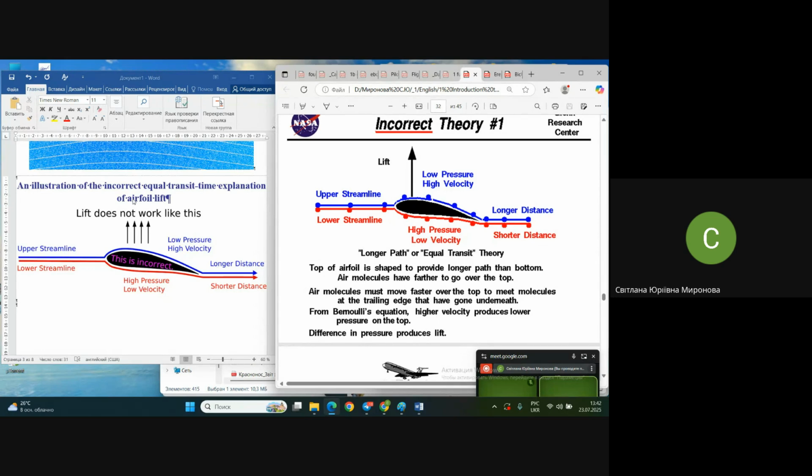And as to the flight principle, this Bernoulli principle, this aerodynamical principle, helps us understand how lift may appear due to different pressure over the wing and under the wing. But why is pressure different? Because speed is different. But why is speed different? It's another story, a story about circulation of the velocity vector. Not right now.